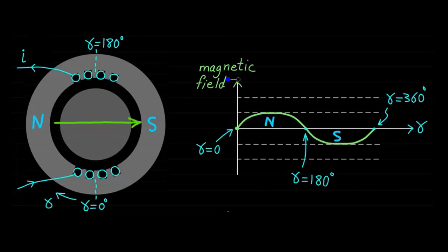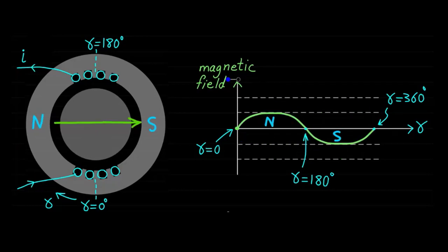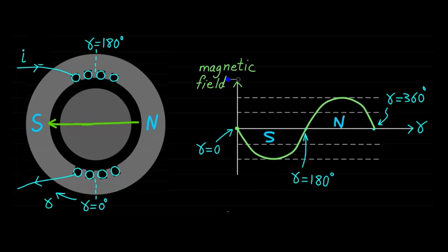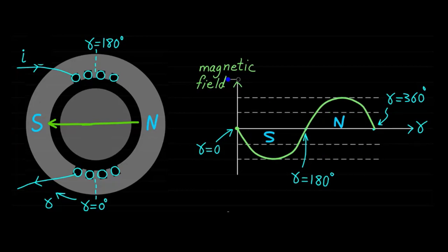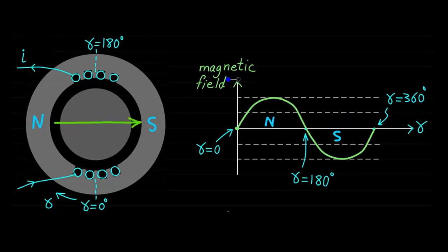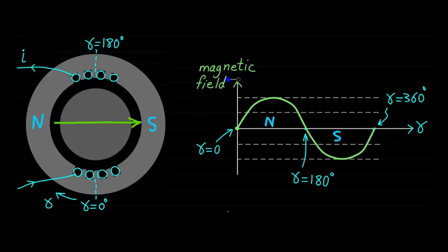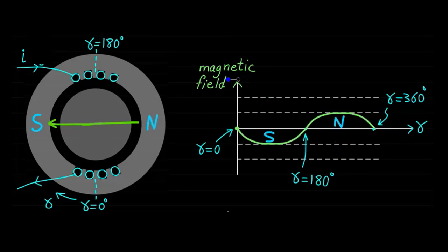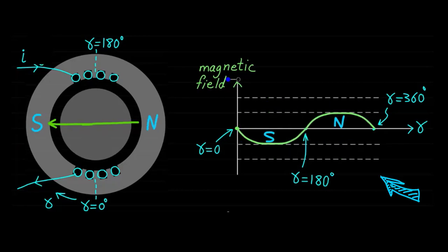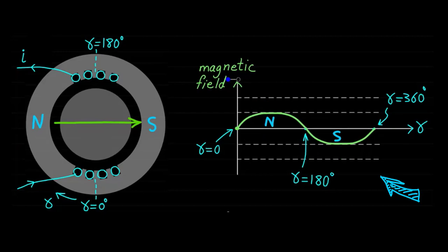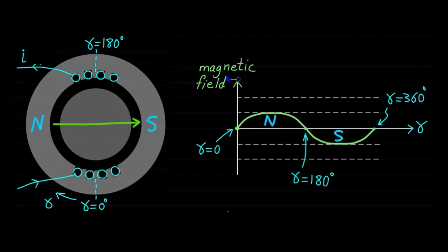It is very interesting to know that the magnetic field waveform distribution is not traveling. That means there is no shift to the right or left in the magnetic field waveform of the single-phase stator winding when it is excited by AC current. Note that waveforms with such behavior can be called standing waveforms, non-rotating waveforms, or non-traveling waveforms.